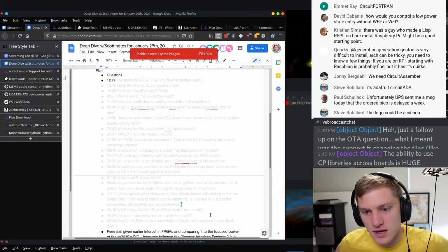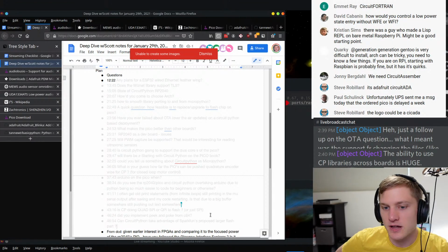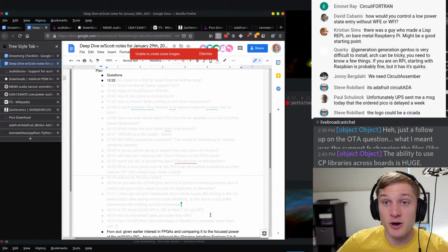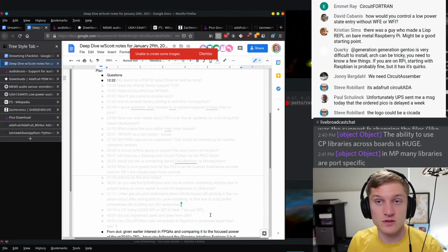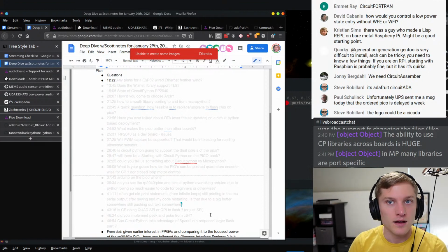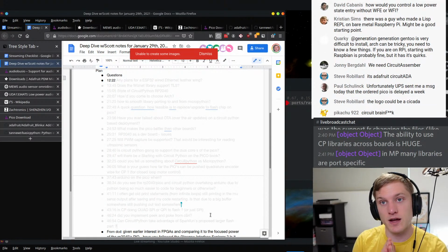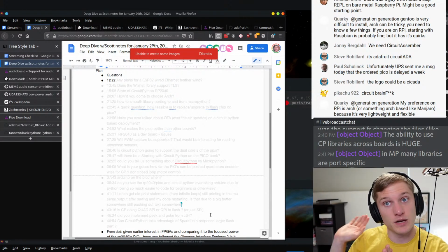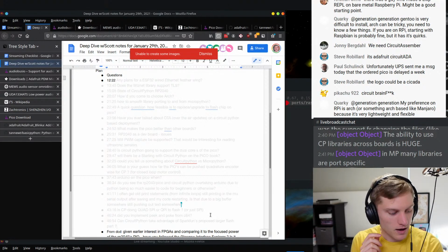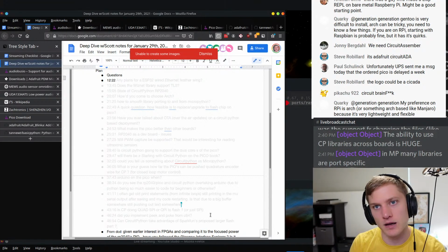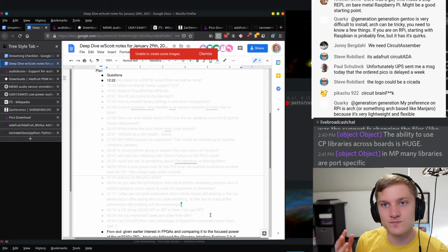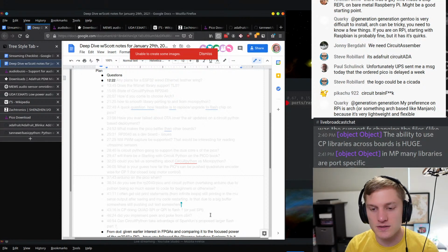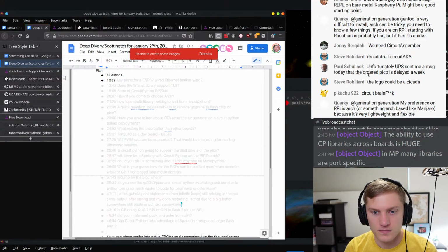Davey asks, can CircuitPython take advantage of Sparkfun's proposed larger flash part? Not in its current form, but my hope is to get all the flash stuff refactored so that by the time the boards are actually available, we can. And the way that it will do that is we've allocated a megabyte at the start of Flash for CircuitPython, and then the remaining megabytes, however many they are, will just show up in your CircuitPy drive. And in fact, I think we're planning on putting a 4 megabyte one on the Feather, although no promises until it's actually released.